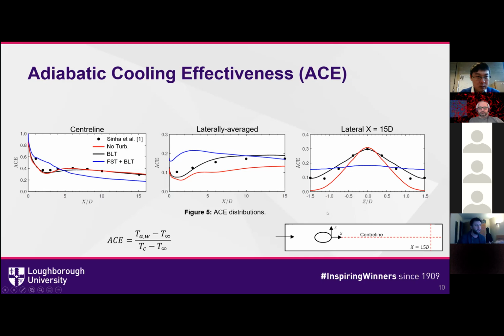So first of all, this suggests that introducing boundary layer turbulence is correctly exhibiting the right coolant spread that we need for these machine learning augmented turbulence model developments that we're pursuing. But by not considering inflow turbulence, you're drastically reducing the cooling effectiveness.